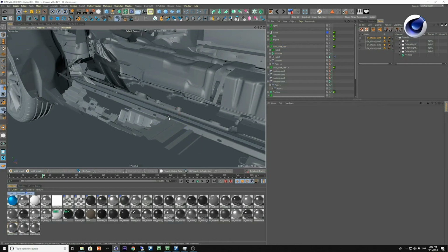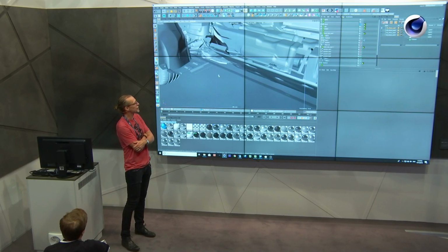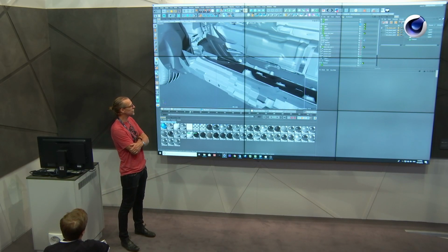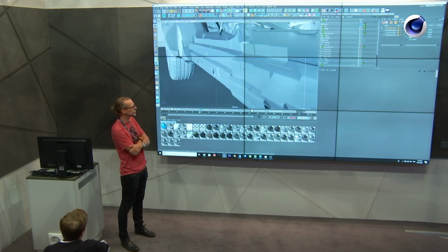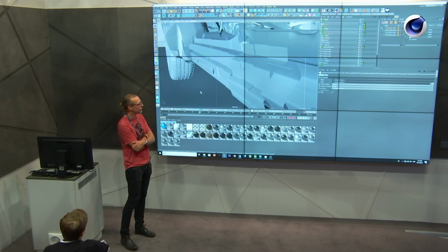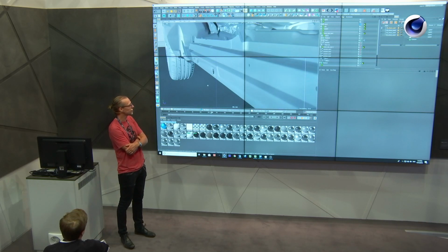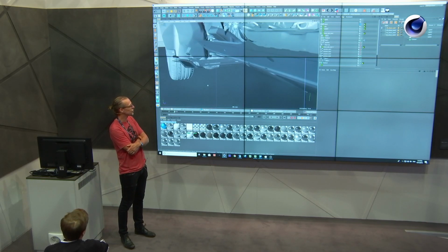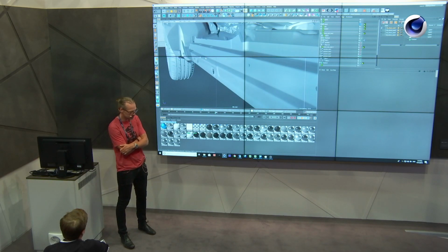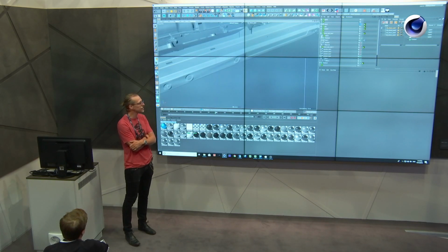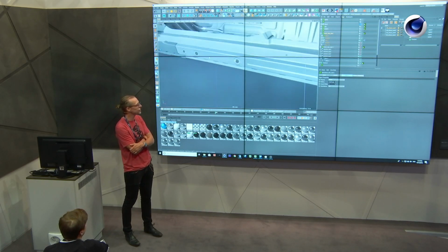The last topic I like to show is custom fall-offing. In doing this type of animation, how an object enters and exits its animation life is crucial. The way that you do this is with custom fall-offs. The fall-offs are controlled inside the fall-off tab of the effector.